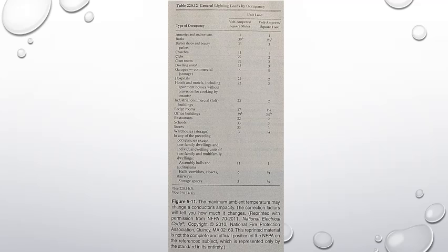For example, a run of conduit to a kitchen will contain 7 THHN current carrying conductors, 1 for a 50 amp oven and 6 for various 20 amp appliances and receptacles. According to Table 310.15(B)(16), the 50 amp conductor should be 8 AWG and the 20 amp conductor should be 12 AWG.